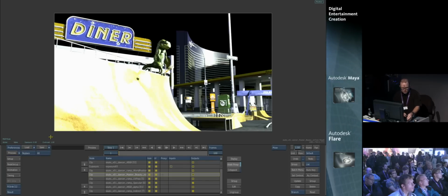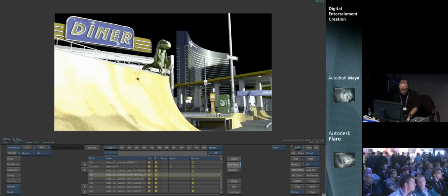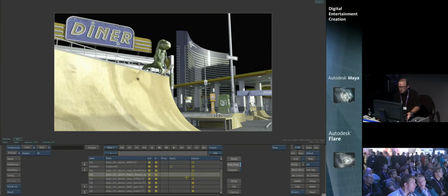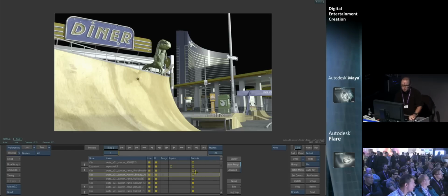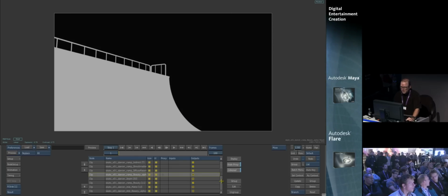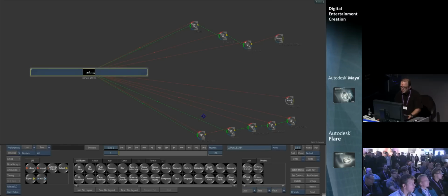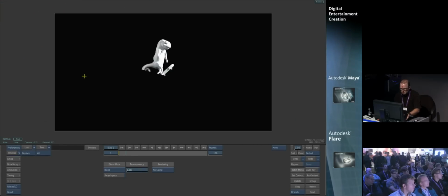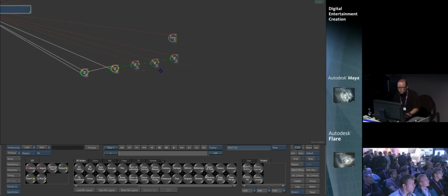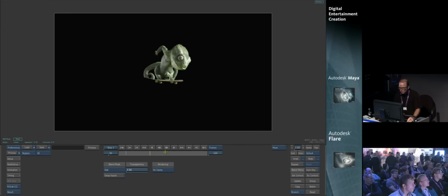let me take all the raw pieces here, and I'll just switch into my scene linear mode and set a working exposure that I like. I would dial this in for real with a proper photo mapper or tone mapper at the end of my pipe, but I'm going to just go ahead and spin through my assets so you can see that we deliberately broke things into layers to allow more flexibility, and you'll see just why. I've got my comp here with the different pieces, so this is essentially a lighting diffuse all the way through to a specular and incandescent build of your shot here.